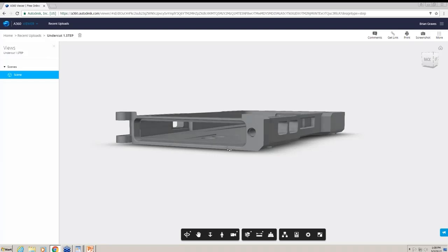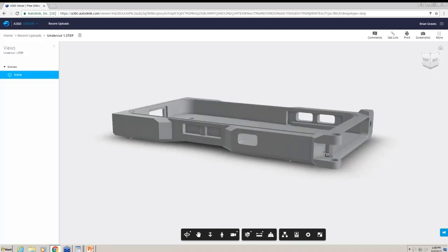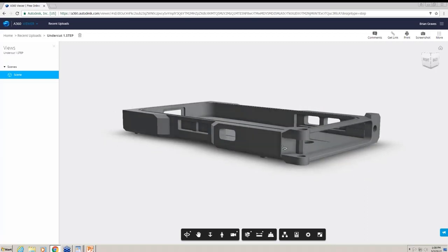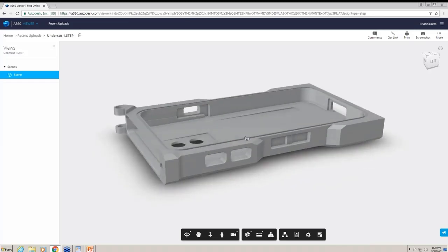This obviously has something slide into it, and then we actually have a little hinge feature over here. All these little areas are considered to be undercuts. Very functional to the part design and what they're trying to do with the assembly. Ultimately for this molded part, it makes the mold very complex simply because we cannot create these.